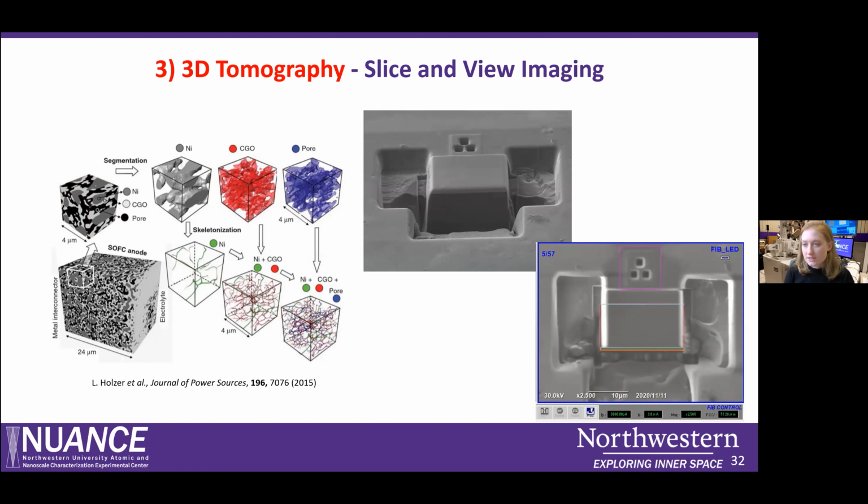The software for the FIB allows you to designate the thickness of a series of slices that you slice away from your block, and then capture an SEM image after each slice. There's a little animation here, probably not the best sample to show this, but it shows the FIB slicing away and the SEM capturing an image.